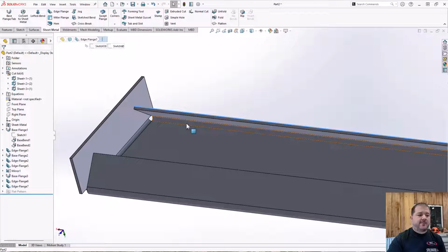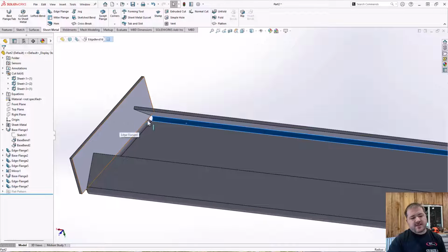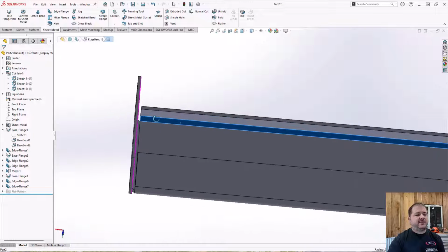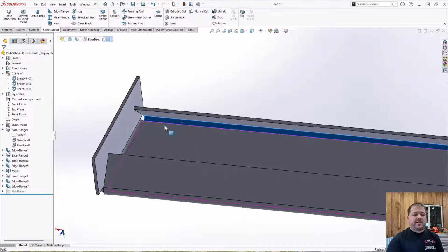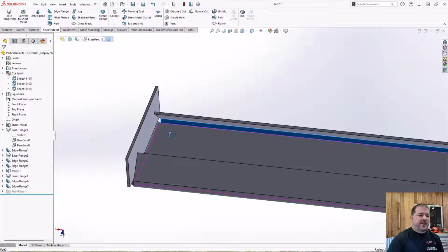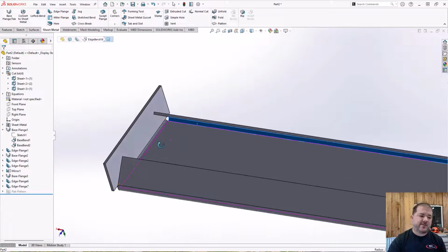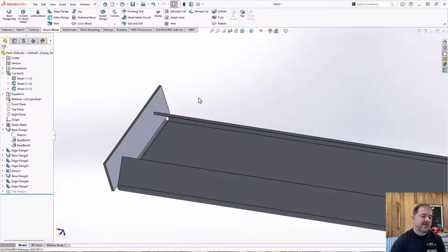And when we do that, this top bend, or this top die that comes in to do this bend, is going to have to fit in between these ears. If you don't want that ear to be in the way, you would have to swap the order of operations, but of course we can't do that. We've already determined, and so you sort of start to get this issue where you're trying to map out which order of operations is going to be the best.